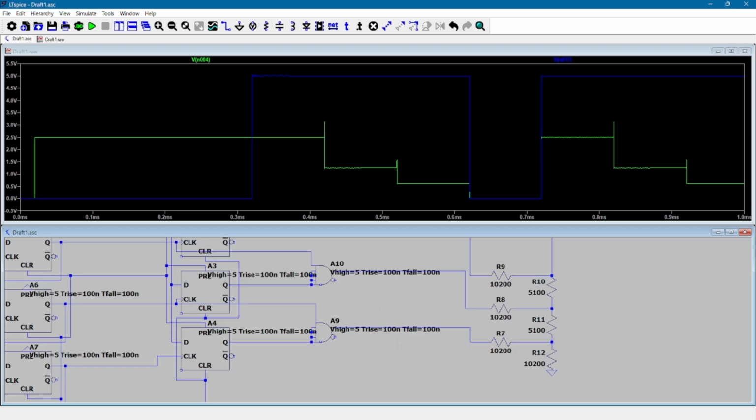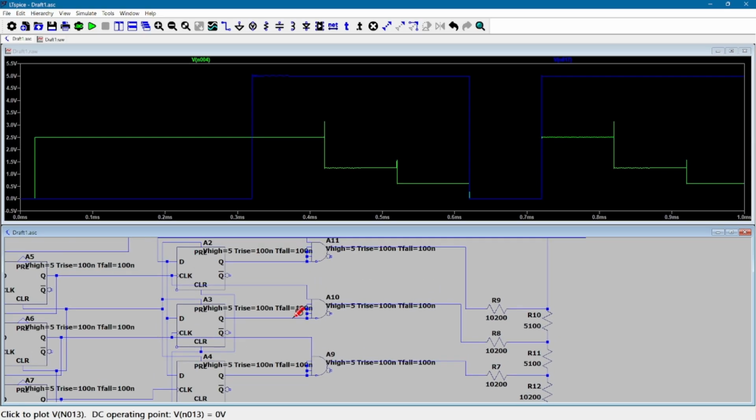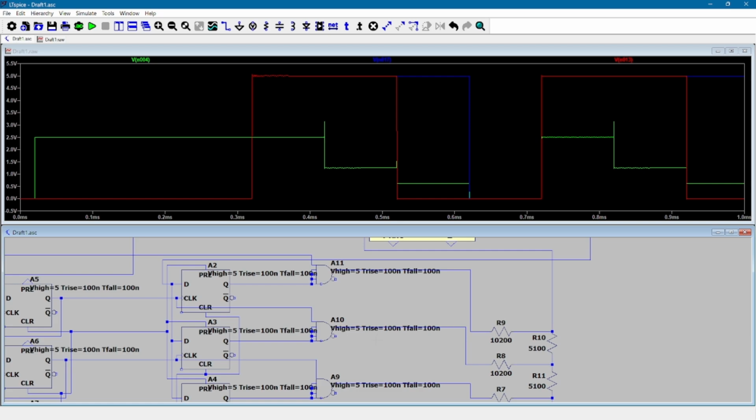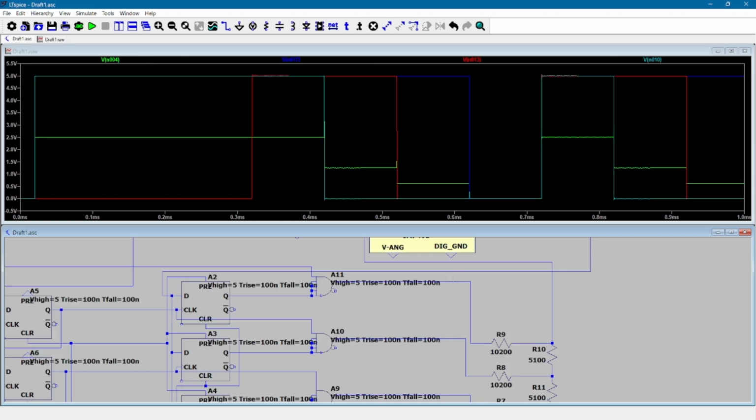Then the sequencer pulses the next gate, and the DAC adds 1.25 volts to the previous 2.5 volts, which tests 3.75 volts. Since 3 volts is less than 3.75 volts, this will be a low. Again, the comparator sends a low, and then register A3 latches 0. The sequencer A2 pulses its final gate, and the DAC tests 2.5 volts plus 0.625 volts, which is 3.125 volts. Again, since 3 volts is less than that, this will also be a 0.